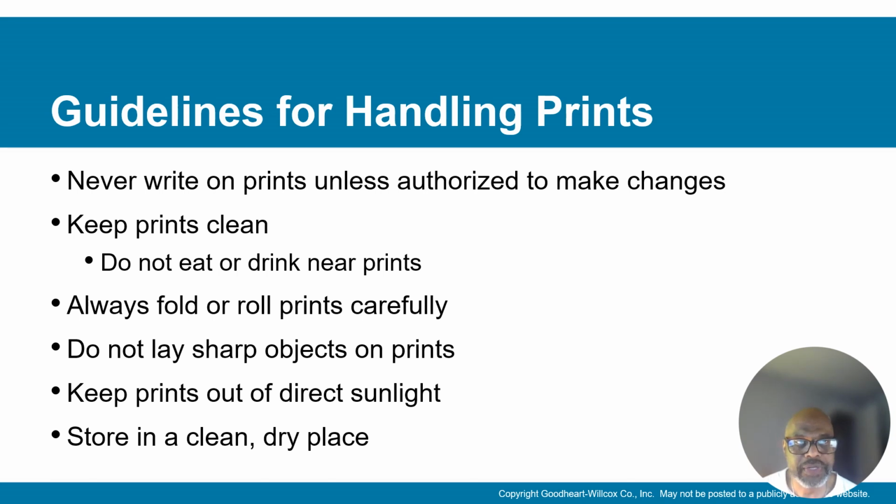So here's the things that you never write on prints unless authorized to make changes. The reason is that somebody may see something that you're thinking about and may think that's how it should be, and they may change something, and it may not be correct. Keep prints clean. They usually store prints in a separate place. On the job site, they will usually have a print table that's set aside from all the dust and things.